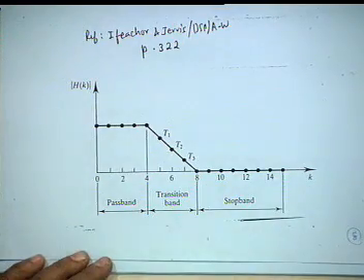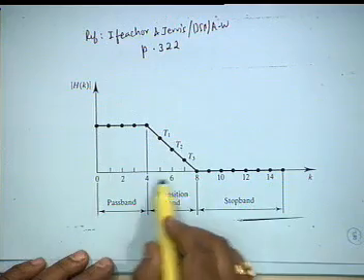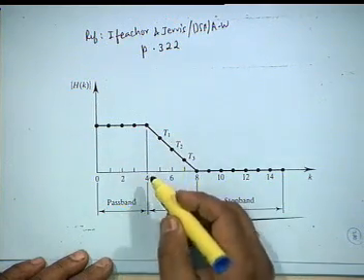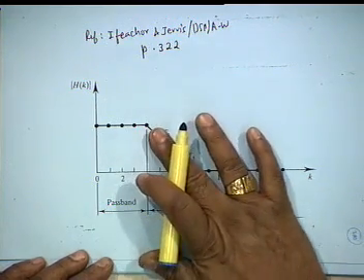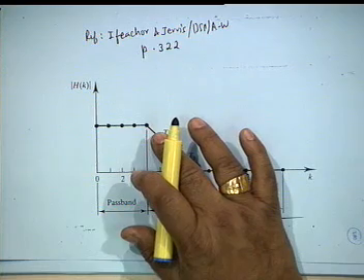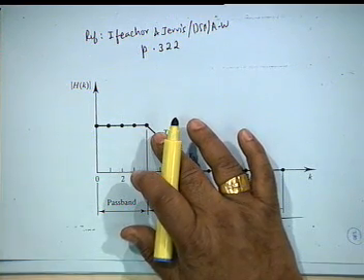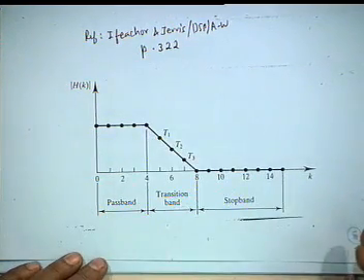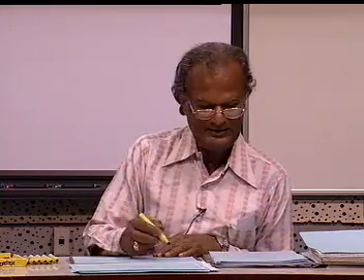So, capital N is 29, but you require only the first 4 if you do not allow any transition, or 5 if you allow one sample in the transition, or 6 or 7 depending on what you want. Is the point clear? So, you do not have to bother about the length being 29.